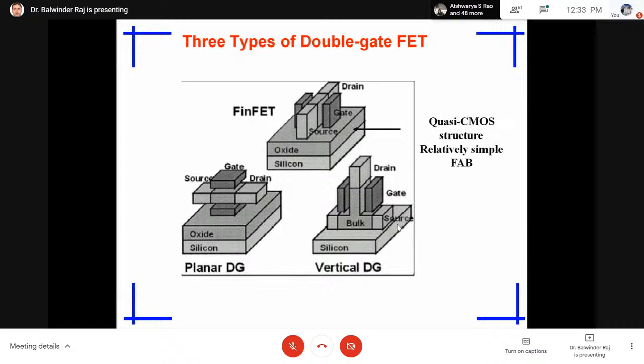How do we increase the density in the vertical? The question is how we can increase the density. In early days, we got both NMOS and PMOS on the same wafer, because ultimately these devices will be used to design the circuit. And in a circuit, if we take the example of a simple inverter, in the inverter also we require two devices, one is NMOS and the other is PMOS, N FinFET, P FinFET. So in early days, in the planar technology, we had these devices on the same wafer in the same plane.